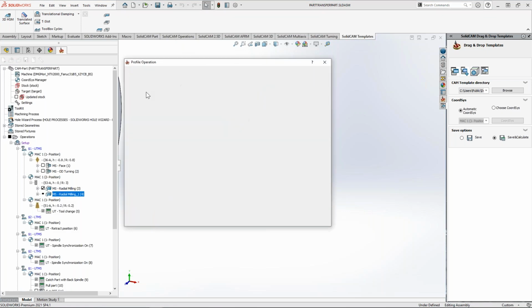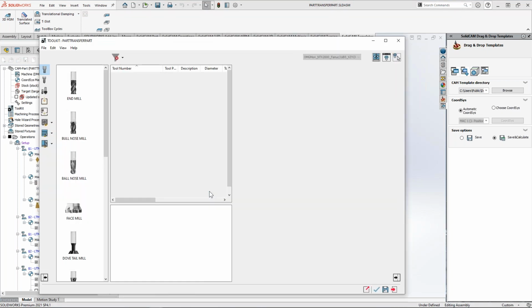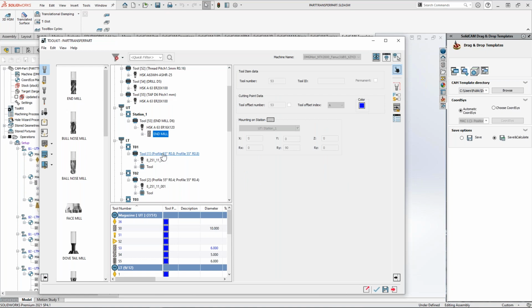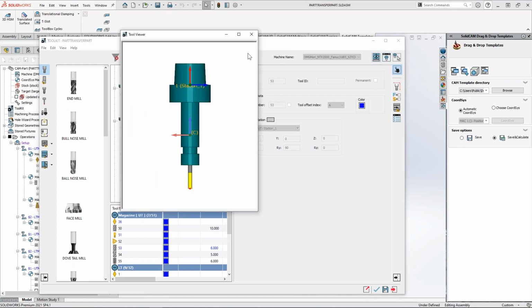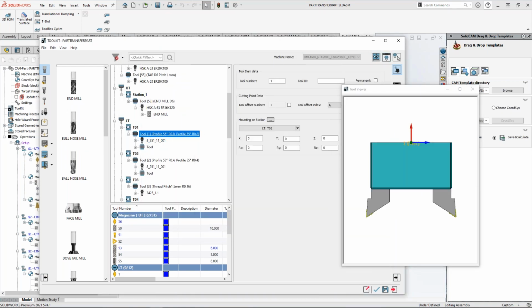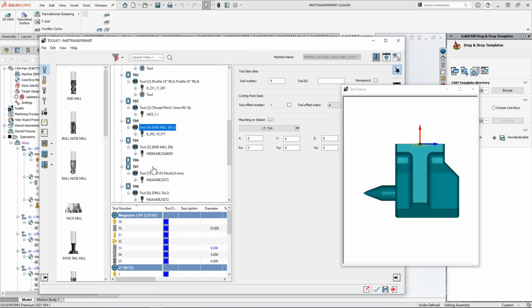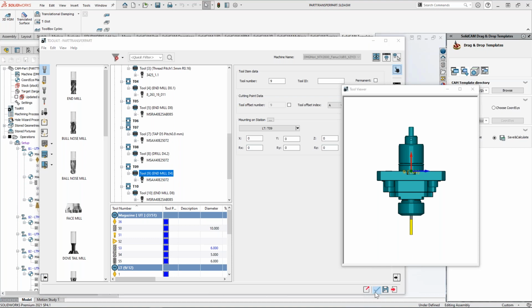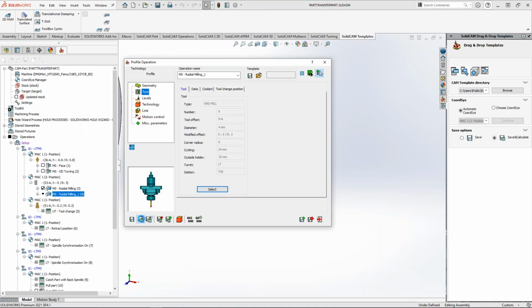Let me find the proper tool. And for the tool, I can also go with my advanced view maybe. I'm going to open my tool viewer and let me find the appropriate tool for this. This is for the face. Here's the one for the radial, but this is roughing. Here we go. I'll use tool number 9. Right. I'll just save and calculate. I'm pretty fine with this. And I'm just going to generate the G code.